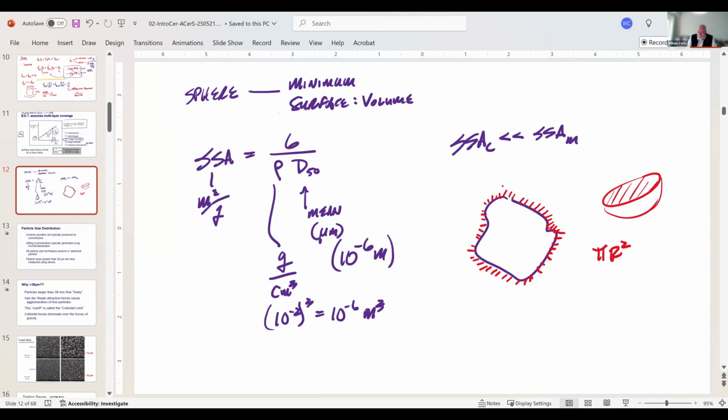So in specific surface area measurements, the measurement that you get from the instrument will predict a much smaller particle size than you measure through particle size techniques. That means your D50, based on specific surface area, will be much, much less than your D50 measured.